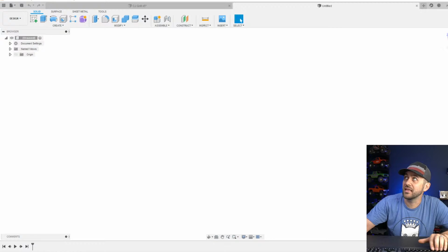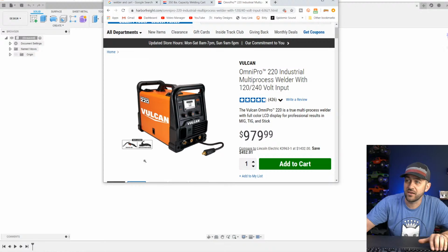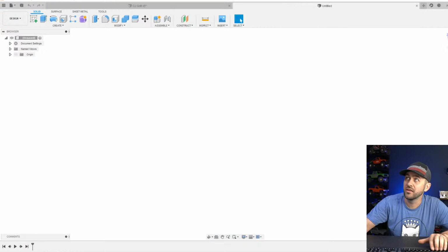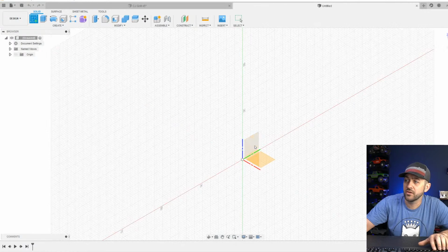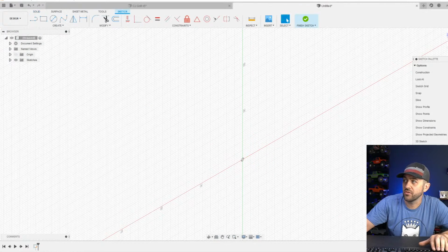Let's start with that center section of this thing, the center orange section, which is going to be very simple and rectangular. So we're going to start a new sketch at the top. Just trying to adjust things so I can see what I need to on all of my screens. Okay, we're going to start a new drawing on the right plane.